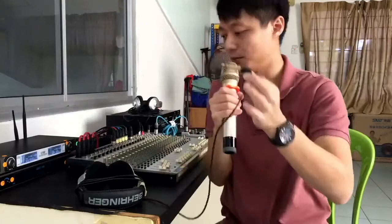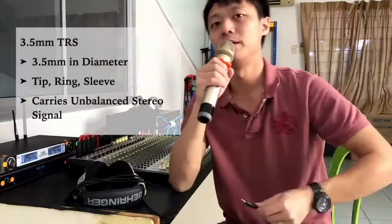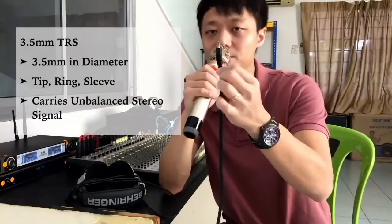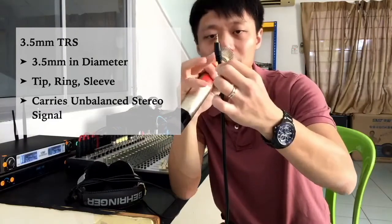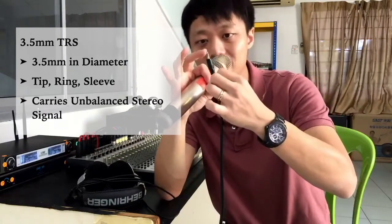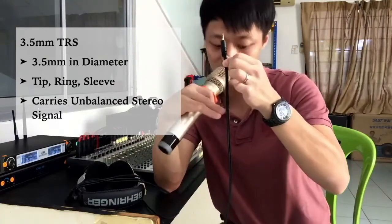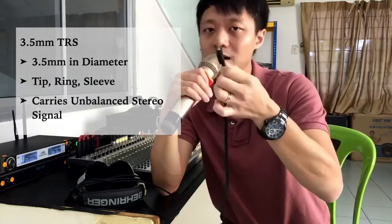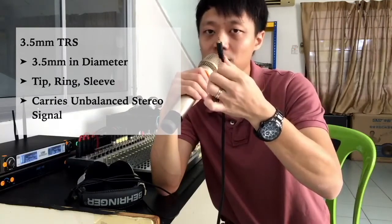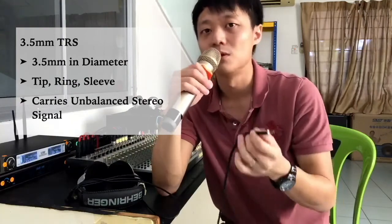Okay, so the third and last connector that I want to talk to you about is the 3.5mm connector. This is a 3.5mm connector because the diameter is so small, 3.5mm only, and it's TRS because it has tip, ring, and sleeve. So it's called a TRS, and in this case, it's used to carry stereo unbalanced signal. Okay, TRS, we normally use them for our headsets and in our phone. That's the most common use for this kind of connector.